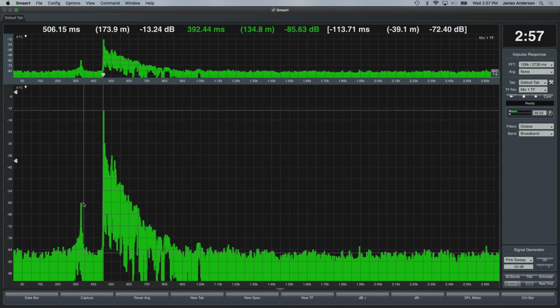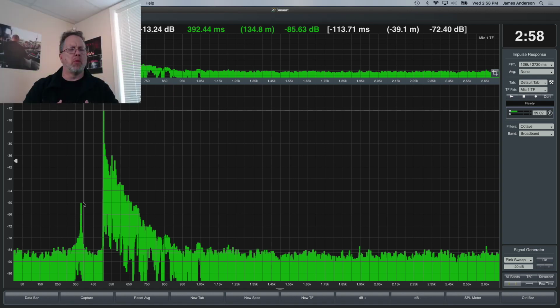Generally, the standard for impulse response measurements is to use a sweep sine, and for laboratory measurements, there are a lot of things that are great about a complex noise source. And I'll let you into my mode of thought: I want to measure the system the way we're going to excite the system. I'm not trying to get an anechoic measurement of the system. I can't go to a person listening to a show and tell them just pay attention to the direct sound and ignore the room. It would be nice if we could do that.